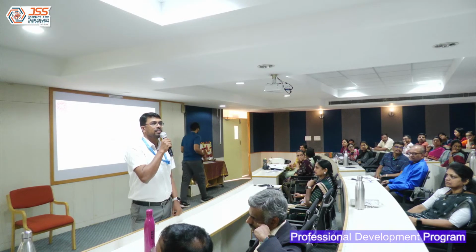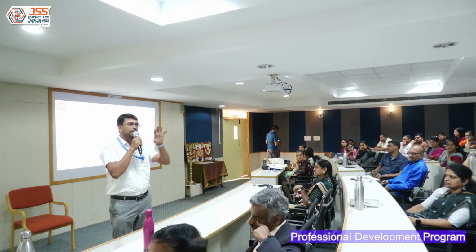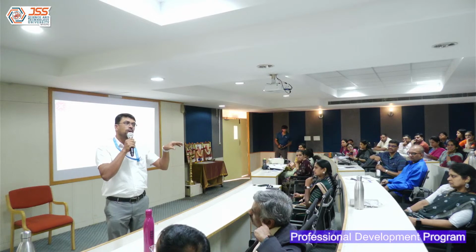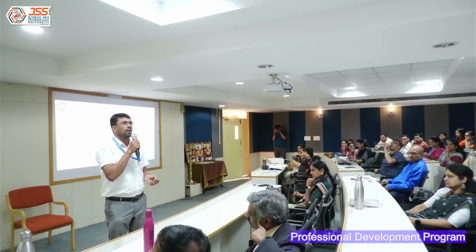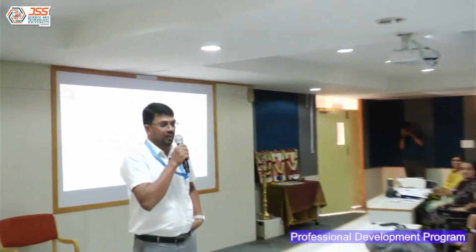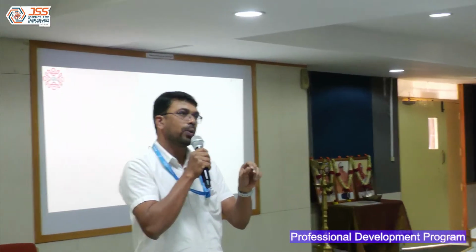My question is, when it comes to scan chain reordering, are you going to test each and every block? No, scan chain reordering is something different. You have a scan chain, and for a certain reason you say I cannot go with this order of the scan chain, so I want to reorder. The purpose of scan chain reordering is to optimize. Scan chain reordering is a requirement which arises from PD.